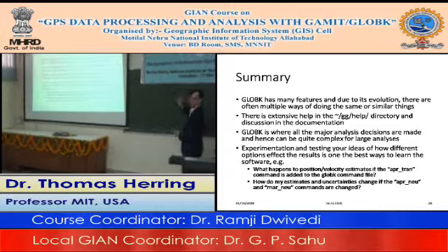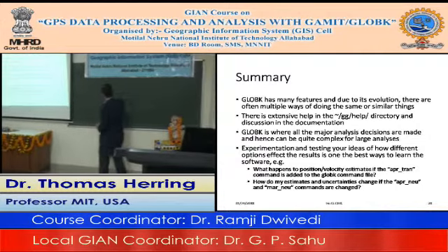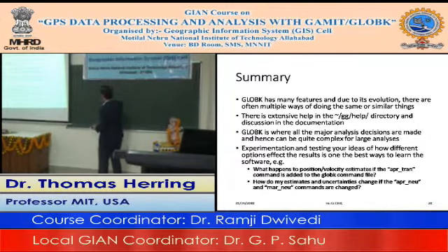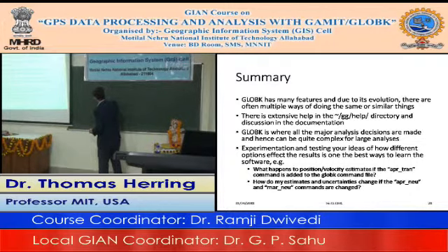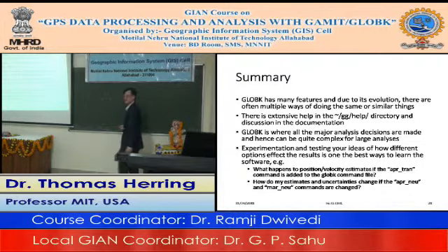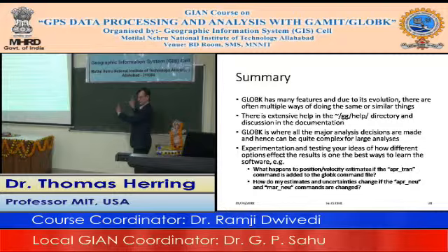So say that's what my network looks like. Now, just for the simple case, I'll form double differences between these stations like that, and I'm going to form double differences between these stations like that. That's perfectly legitimate.